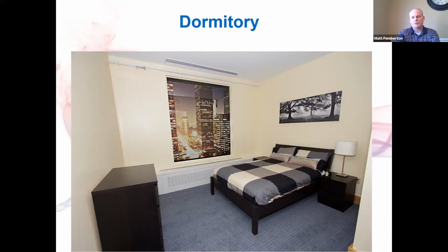If you grabbed any manufacturer's catalog and flipped through it, you would notice that there are 5 to 12, depending on the manufacturer, different types of chilled beams. The reason there are different types is because there are different ceiling types. We put them in drop ceilings, hard lid ceilings, and bulkheads. All these different applications allow us to still use induction style chilled beam systems with all the different types of ceilings. Along the floor here, you will also see a perimeter induction unit, which is really just a chilled beam that's now by the floor instead of the ceiling.